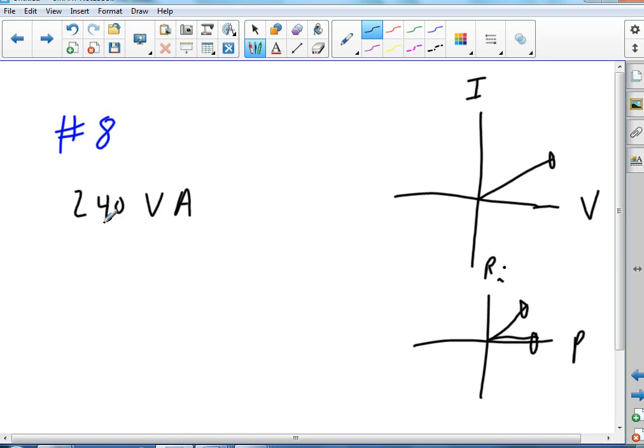Okay. 3 phases, induction motor with a 90% power factor. That sounds cool. So the volt amp measurement is the apparent measurement, and that's why we call it volt amps. If it was real, then we'd call it watts. 90% power factor. Okay, so what do I want to find? The real power? Yes. Okay, so power real.